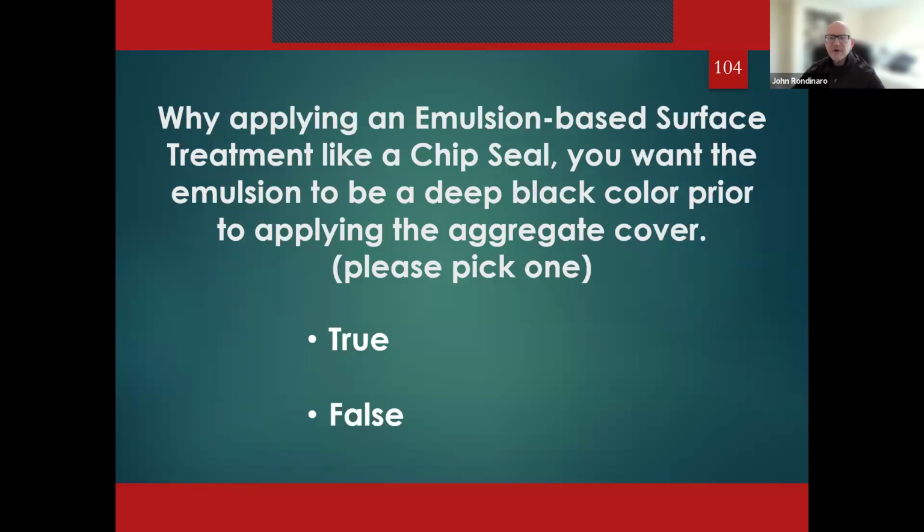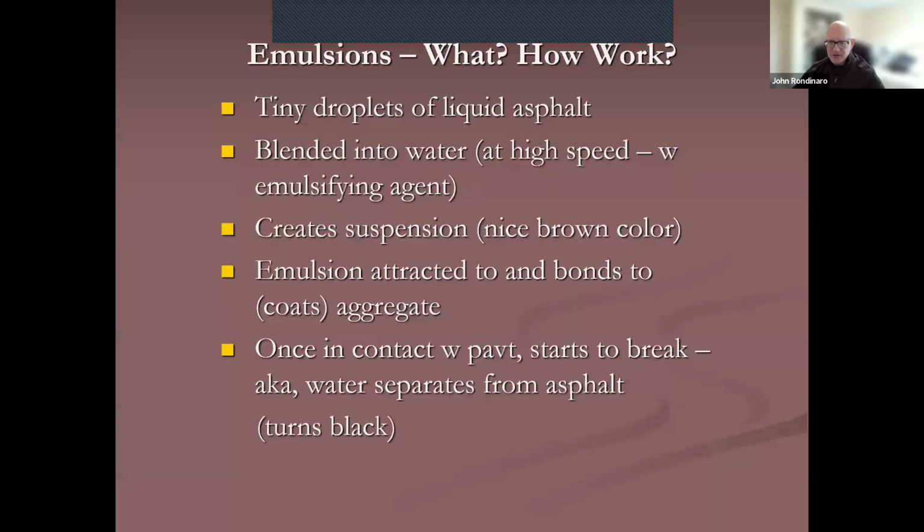All right, folks, everybody's right. That is false. You want that to be a nice chocolate brown color. Once it's turned black, that aggregate's no longer going to stick. So let's talk about our emulsions really quick.